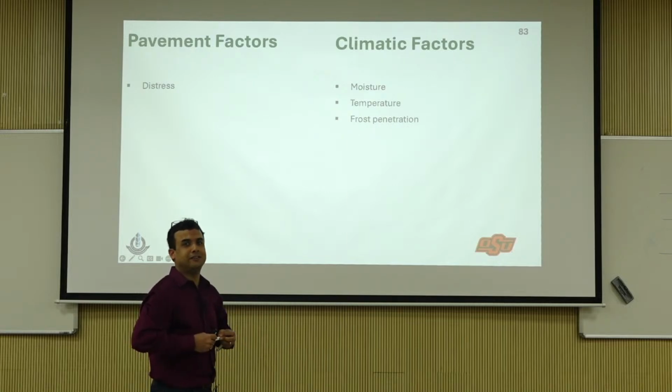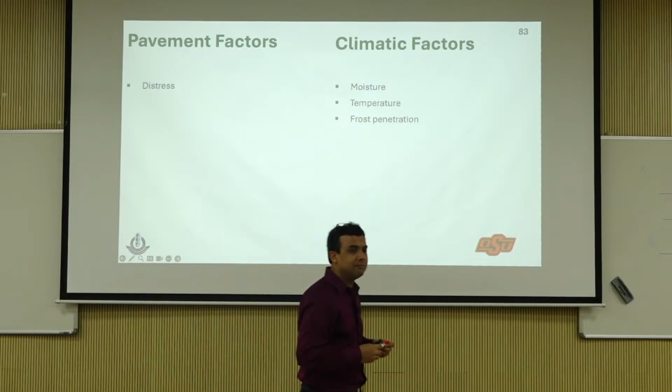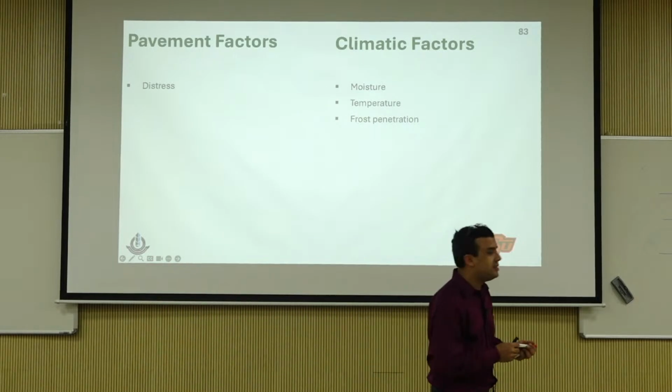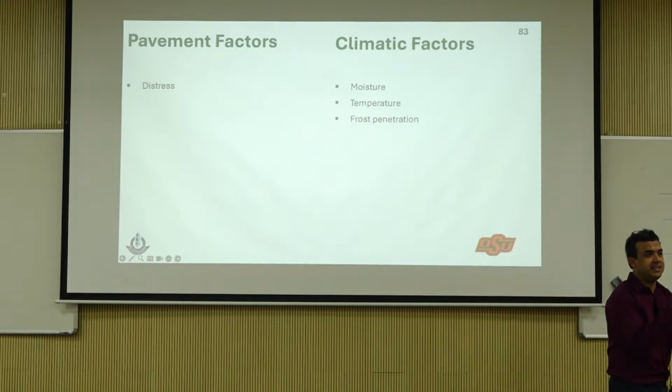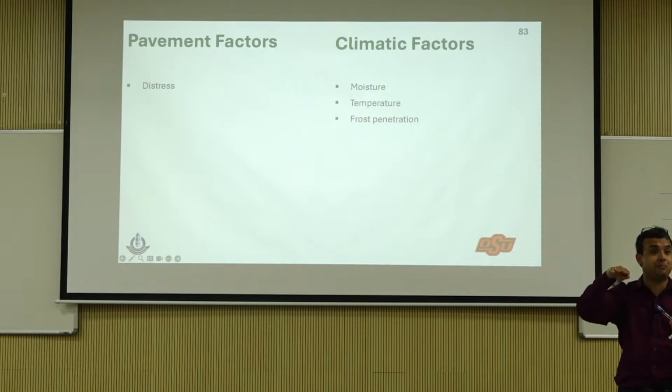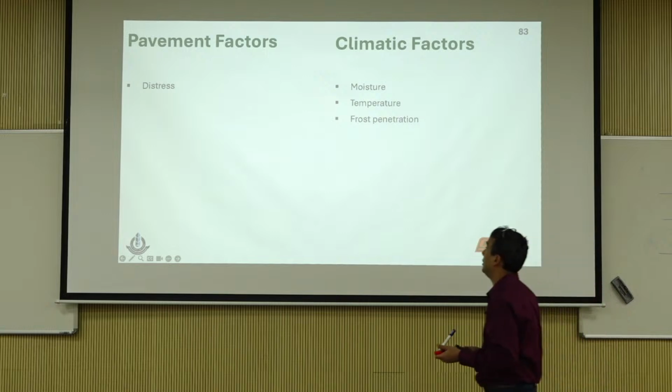Either one is a good answer. Exactly. Because the basin happens because of the load transfer, right? If there is a crack, the load may not transfer. You may actually think that, oh, it's really good pavement, but actually because of a crack, it didn't transfer, right? So it's very important.